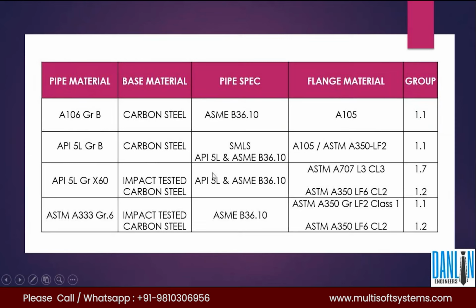So as a stress engineer, he must read all the documents. The process team will provide documents called P&ID and line list. From the piping team, the piping material engineer provides the PMS and the wall thickness calculation. Then the layout team has made the 3D modeling and produces the isometrics and the Navisworks file, and provides them as inputs. So these are all the inputs, and the PFD from the process team.